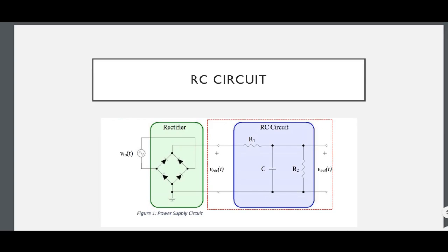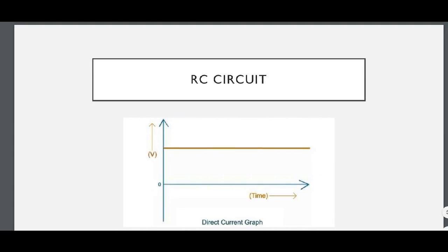And what these components do is they take the curvature and they flatten it out so that it's a direct current, or a DC voltage, which is a straight line. And that is done by using the resistor values, where there is a drop across the resistors and a charge built up on the capacitor that eliminates the increase and decrease of the sine curve.